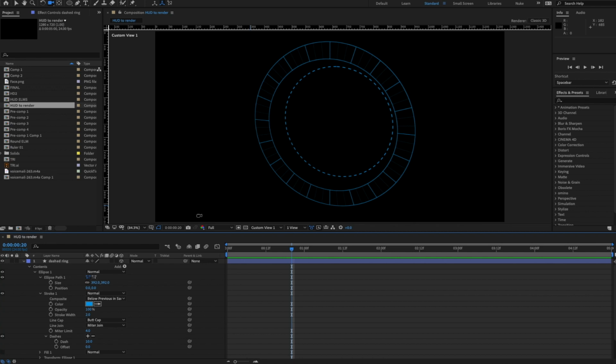One thing I like to do is turn off the mask and shape visibility, so I can actually do this and see what's going on. And also, if I need to, I can even turn off my layer controls. That way I can concentrate on my dashes here and see that I'm not getting any kind of bridging or overlapping.